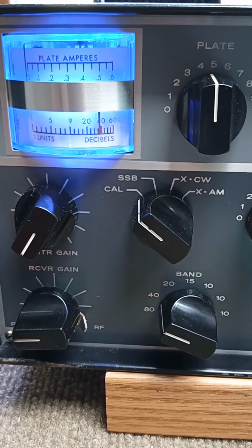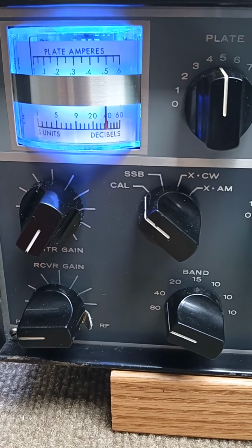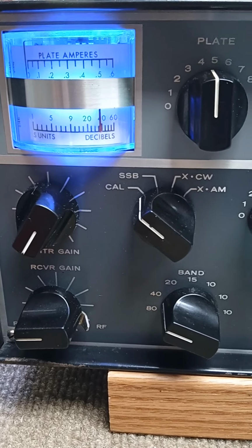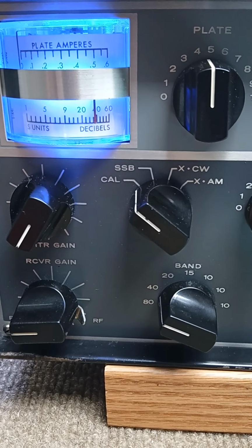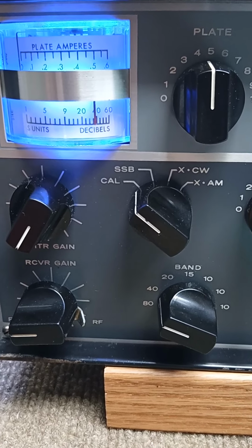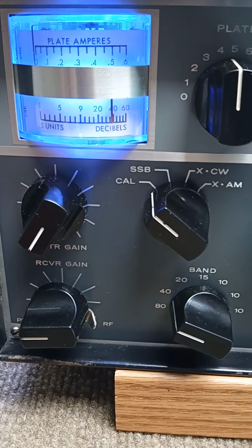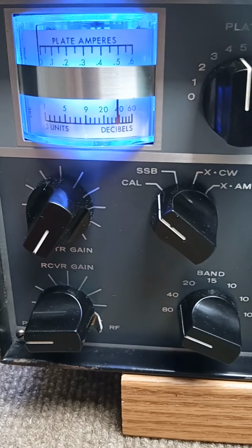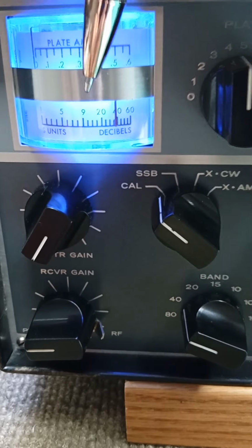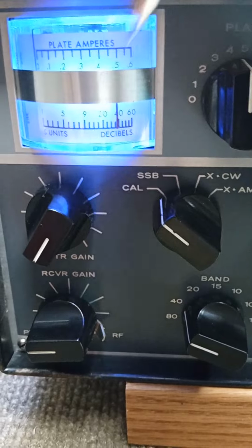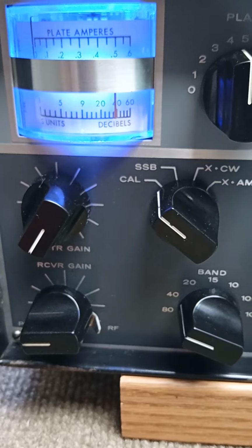The proper filter that I made using absolutely state-of-the-art filter crystals, and never try to build a filter with oscillator crystals. The HC49 oscillator crystals can be as high as 60 ohms series resistance, and that's huge losses. There's more power lost than transferred. But this is the stock marker oscillator crystal on 40 meters, just a shade under 40 over S9. That is, I don't know, 60 dB difference. So putting in the wrong kind of filter results in horrible losses.